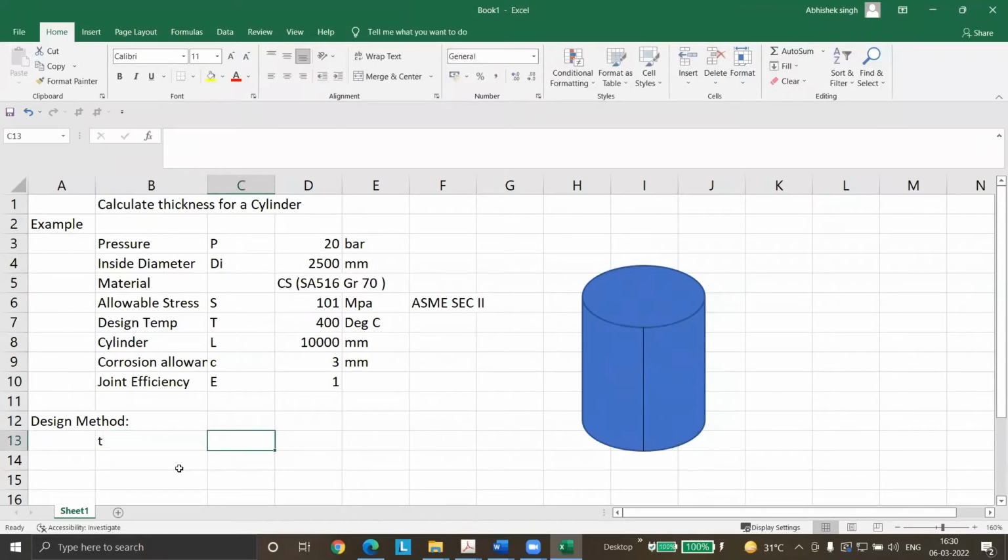Are you guys in line with what we just said, able to visualize, or confused? Clear, right? So I've just written the stress value which you take, PD by 2T. Same thing, T I have taken here because now S is the known thing and our job is to find out the thickness. So in this case, this is the formula I have to use. Clear to everyone?